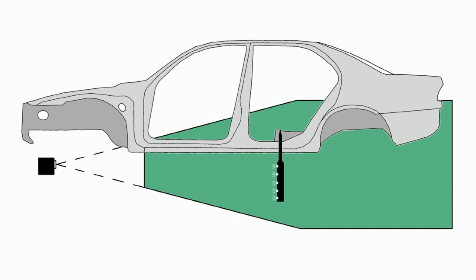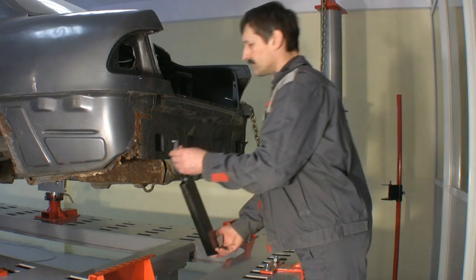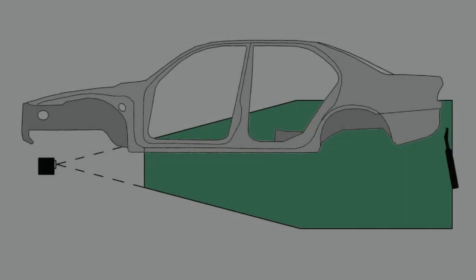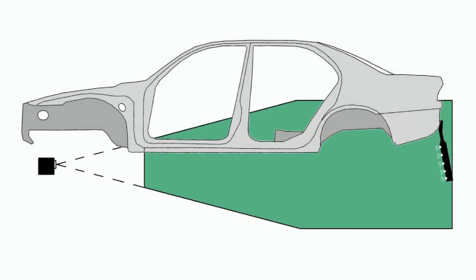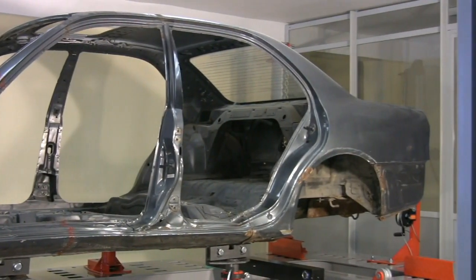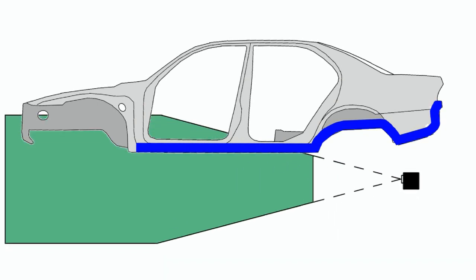Having finished the measurements of the underbody points, we have to complete the series with the measurements of the points located on the rear, using the lateral probe again. So, we have already measured all reference points in the central and the back sections of the vehicle's body. Now, we need to proceed to the measurement of the front section.